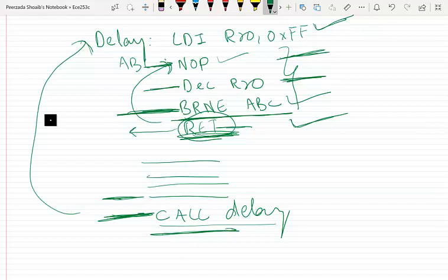You should remember that the instruction below the branch has already been fetched and is next to be executed. But when this instruction was executed, we came to know that the processor has to branch somewhere else. As I have told you, the vast majority of the AVR instructions take only one machine cycle, but some instructions may take 2, 3 or 4 machine cycles, and these instructions are jump, call, return, and all the conditional branch instructions like BRNE, BRLO, and so on.